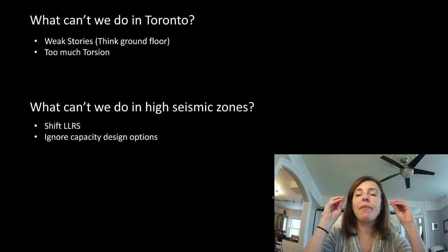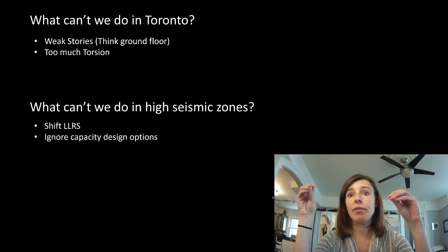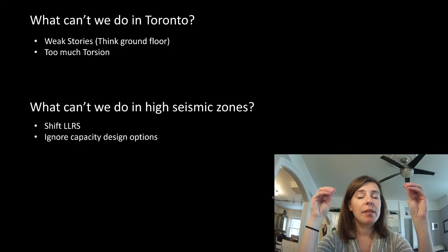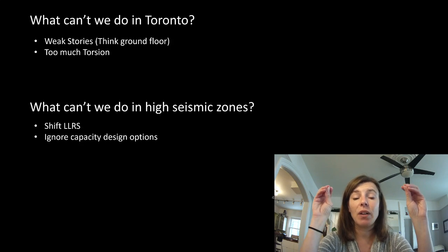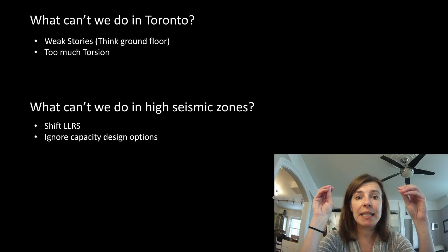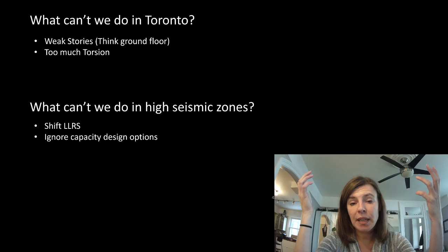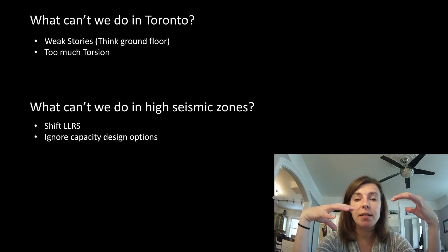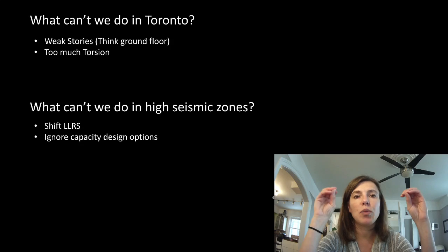So we have to be very precise in making sure our building is not too stiff. So we want it stiff enough, but not too stiff. So you can see that the engineering of that becomes very difficult, especially considering that things like glass and cladding can add stiffness to a building that we might not have used in the strength design. So capacity design becomes a very, very rigorous process.